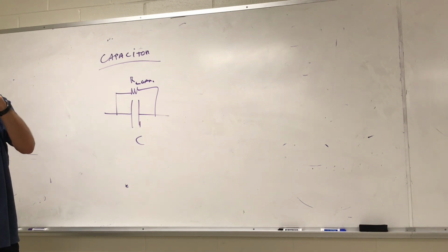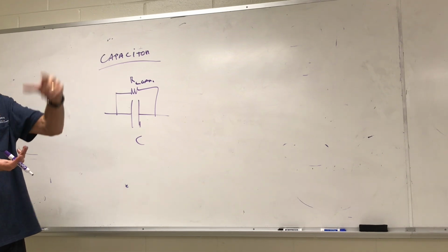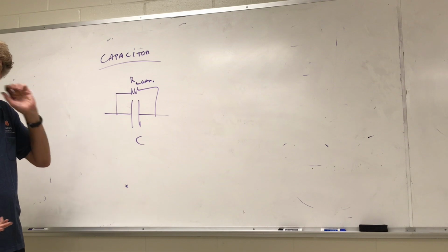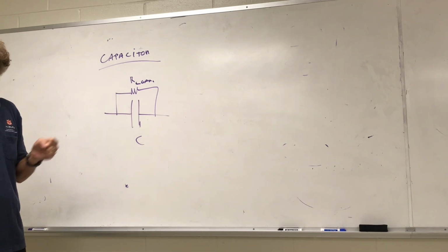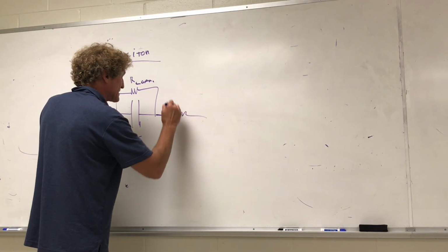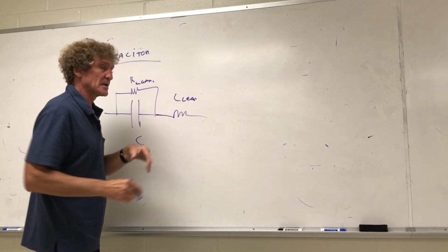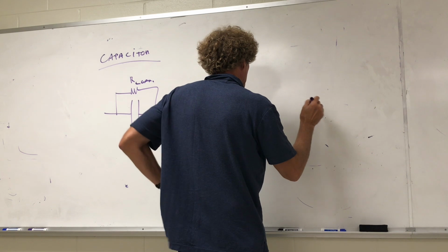The power supply, if you have a full wave rectifier, on the output of that, it always has the same polarity. You put these capacitors on the output of a full wave rectifier, you don't care if you get a little leakage, as long as it isn't a lot. And then you're always going to have an inductance because of the leads. That would be for an electrolytic. The model we use always, because we don't deal with electrolytic capacitors typically, is this.